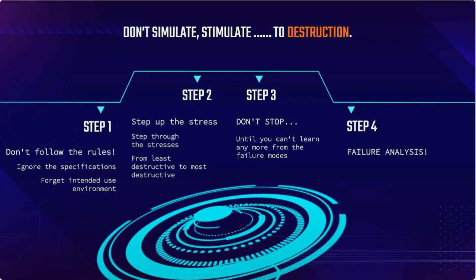Really, you're stopping when an engineer looks at the failure modes you're finding and says, I can't do anything about these without spending a whole lot of money. There's no way to get around these. And that's not the point of HALT. The point of HALT is to find tolerance stack-up issues, or the one particular component that comes off in vibration first because of the way the leads are bent, or basically cherry-picking out the easy-to-fix, easy-to-identify failure modes that will be the ones that show up first in the field.